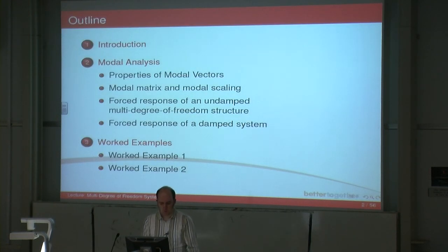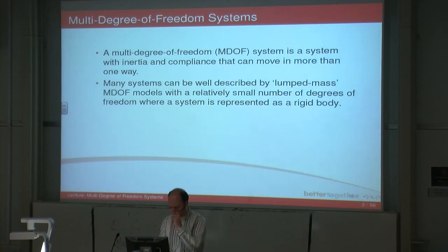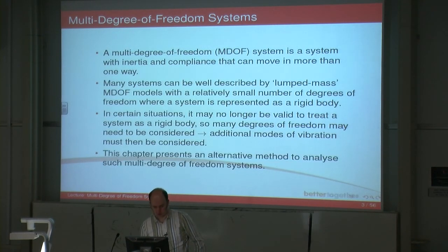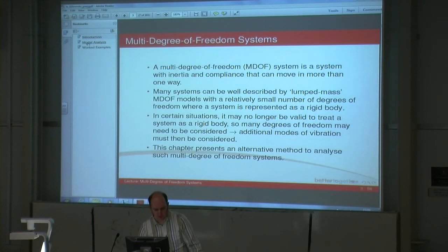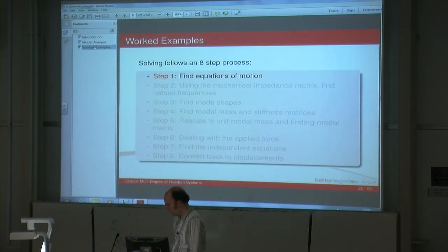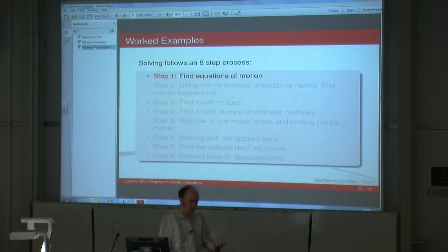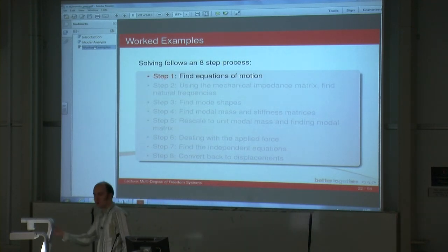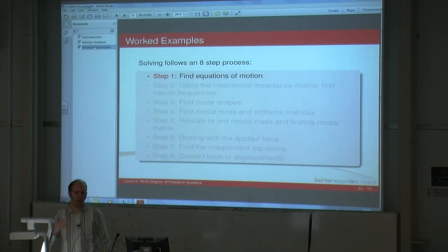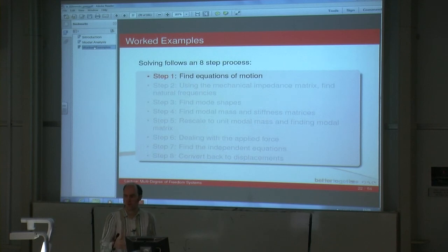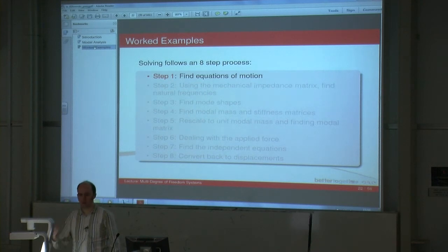Right. So the subject of the lecture was modal analysis, which is a way to deal with problems where you've got lots of modes, lots of degrees of freedom. The issue with the normal process for solving problems with multiple degrees of freedom is you end up with differential equations that are all coupled together. They're linked to each other, and you have to solve them simultaneously. Whereas modal analysis allows us to separate those equations into separate differential equations where you can solve each of them individually, which is a lot easier.